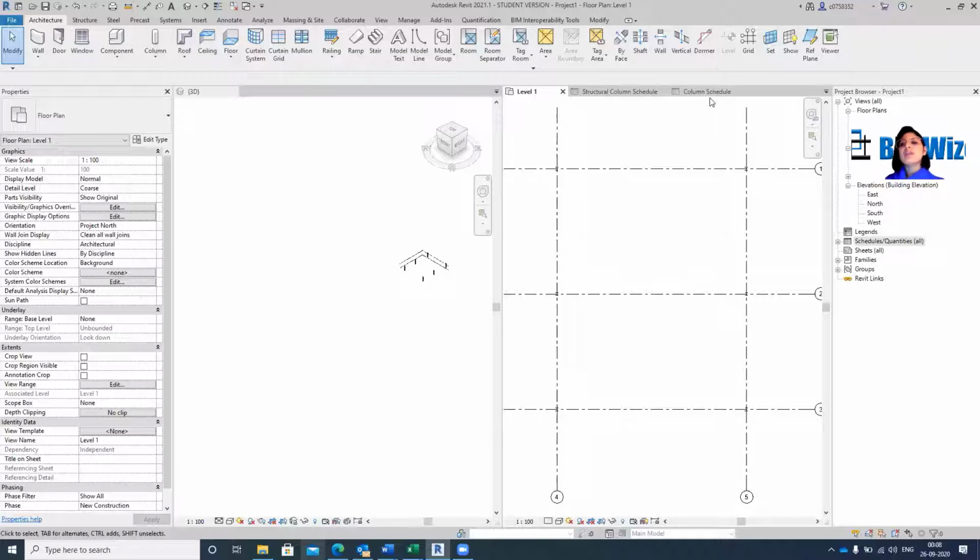Okay, so architectural columns are basically columns that are not load-bearing. These columns are not there for structural purposes. That can be for aesthetic purposes, or they could be columns that surround the structural column. Let's say you have a main structural column. It can be precast concrete, or steel, or even wooden, but if it carries a load, then it's a structural column.